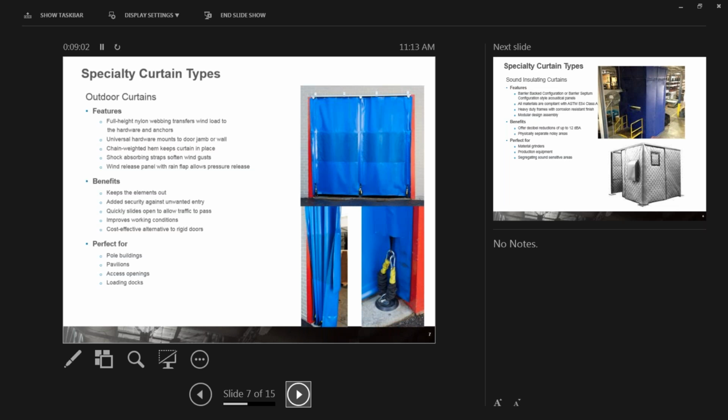Generally, what you'll see is that you have two portions of 18-ounce vinyl on both sides of some sort of insulation, whether that just be foam or that could be some sort of batting material, something just to give you an essential windbreak. But one of the neat things about this is that you see centered on the top picture in the middle of this is there's actually a wind baffle associated with this. The idea of this wind baffle is to allow some air pressure to feed through that door, so it essentially doesn't create a sail and blow this product completely out.